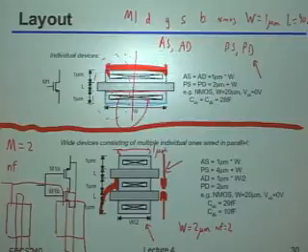Now, again, unfortunately, because there tends to be a lot of confusion around this point, it's not always entirely clear. Somebody may say NF of 2 versus width of 2 and things like that. Basically, make sure that if somebody gives you a schematic or comes to you and gives you an instantiation, you have them sit down and draw what they actually intended this to model. So ask them, did you really mean something where there are literally 2 transistors in parallel?